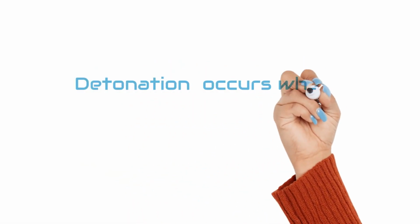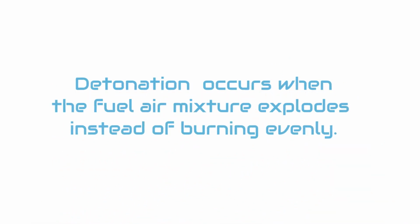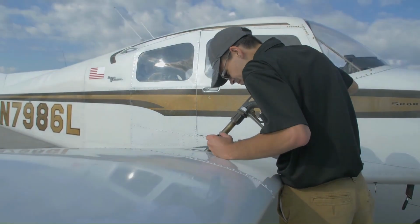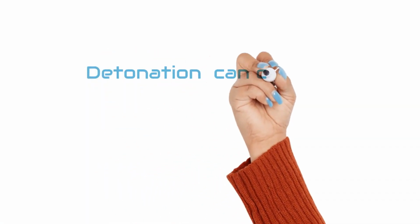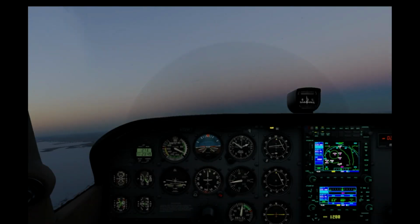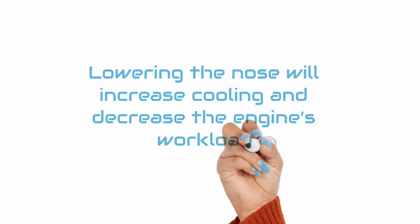Another thing to look out for is detonation, which occurs when the fuel-air mixture explodes instead of burning evenly. Detonation is usually caused by using a lower than specified grade of aviation fuel or by excessive engine temperature. This causes many engine problems, including excessive wear and higher than normal operating temperatures. Lower the nose slightly if you suspect that an engine with a fixed pitch propeller is detonating during climb out or after takeoff. This will increase cooling and decrease the engine's workload.